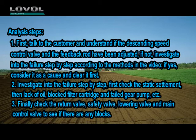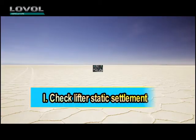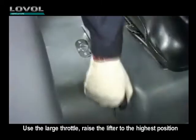First, check the static settlement, then lack of oil, blocked filter cartridge and failed gear pump, etc. 3. Finally, check the return valve, safety valve, lowering valve and main control valve to see if there are any blocks. Check lifter static settlement.